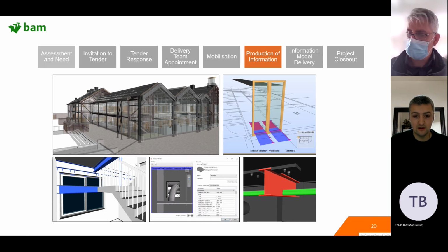You just click a button and you get loads of results for where you've got clashes. In fact, I've got an example of a clash here, bottom left. Well, it's not a hard clash actually. We've got a steel beam right in front of a window. Clash detection wouldn't have picked that one up, because if they're not touching, it's not a clash.